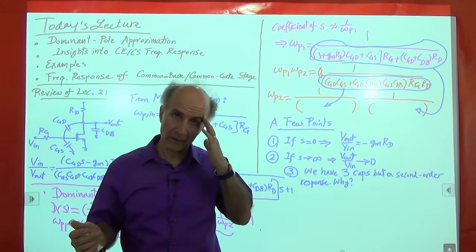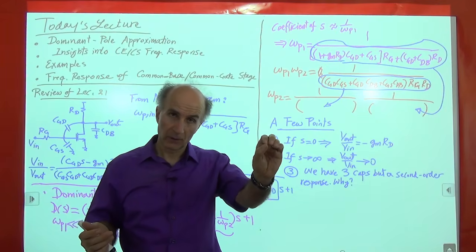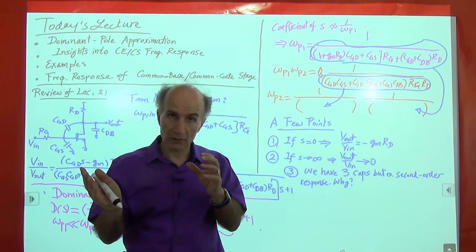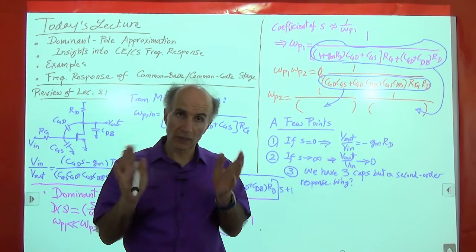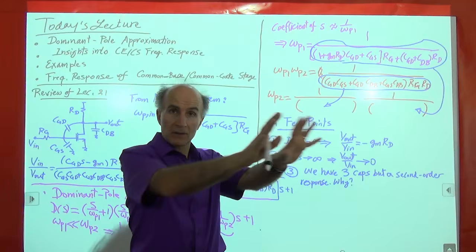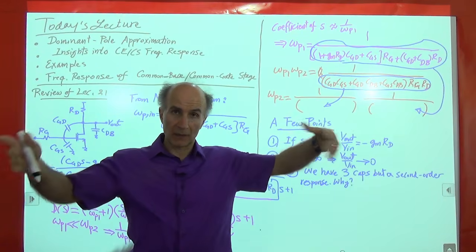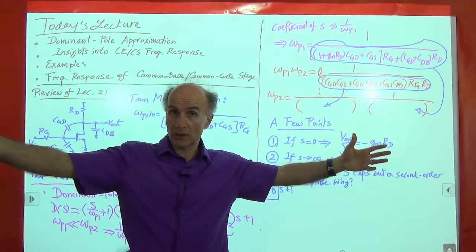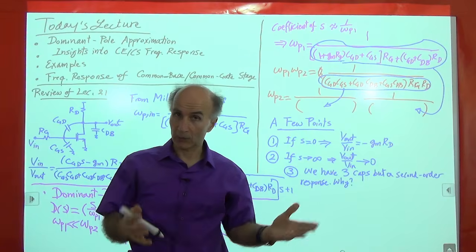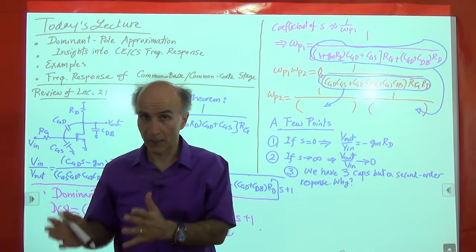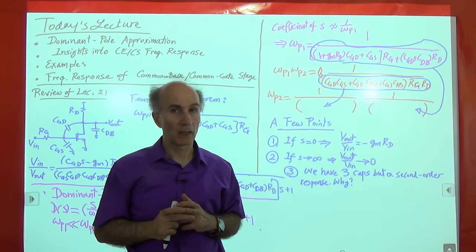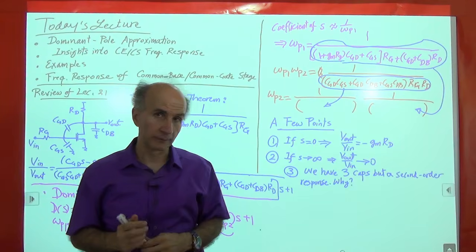And the way we're thinking about this is that for every capacitor and every inductor, we have a differential or integral relationship between the voltage and the current. So when we have n of these in the circuit and we simplify everything, we write out the whole differential equation, it should be an nth order differential equation. So that would indicate that it should be an nth order transfer function. Okay? All right. Well, that's not entirely true.